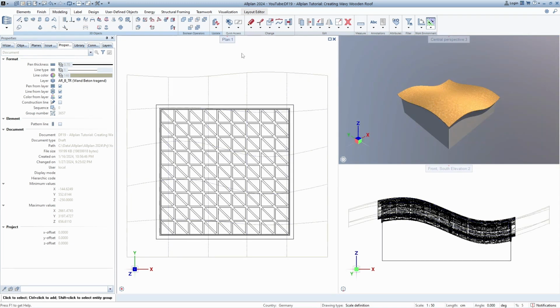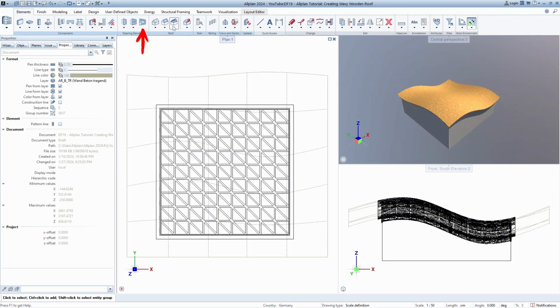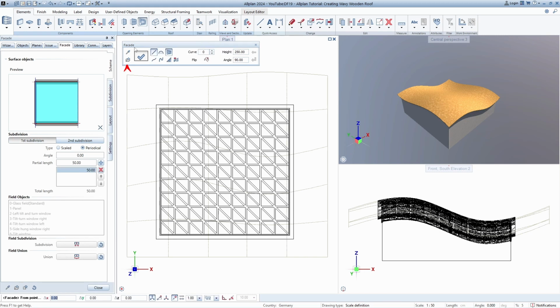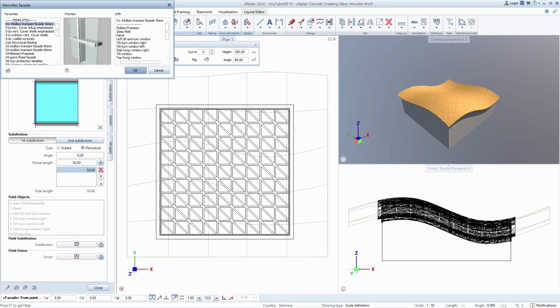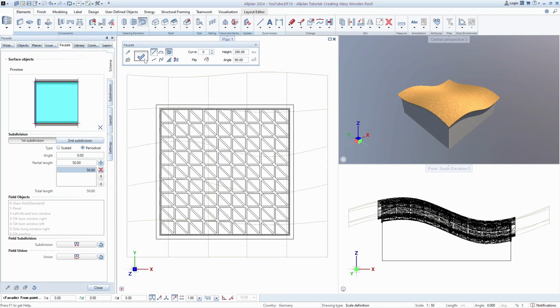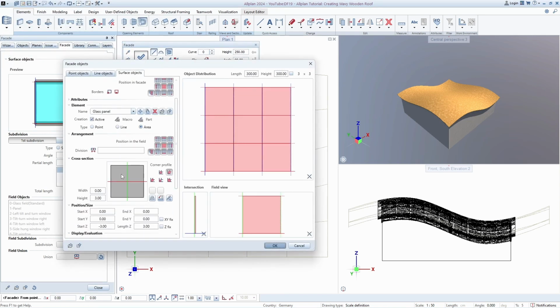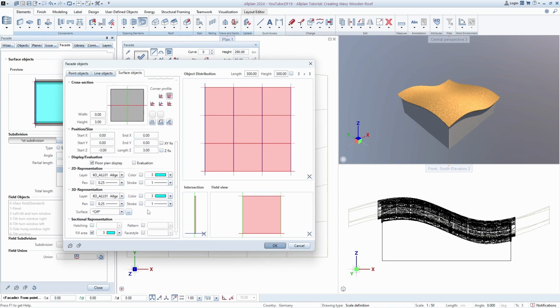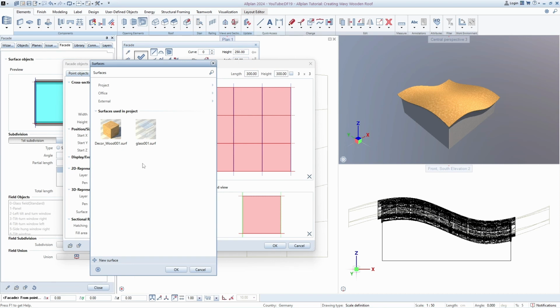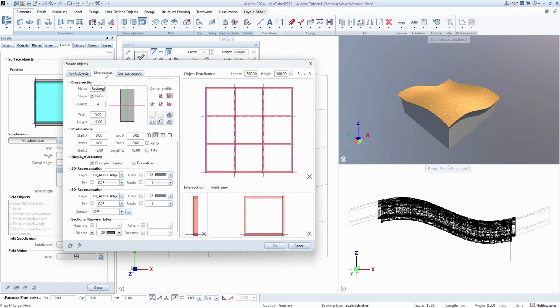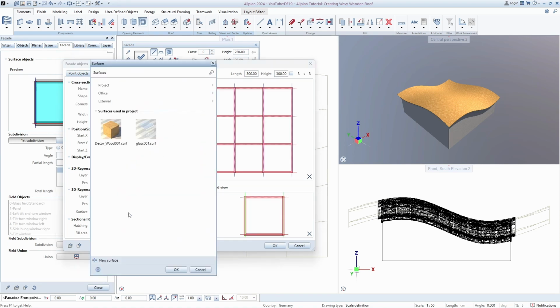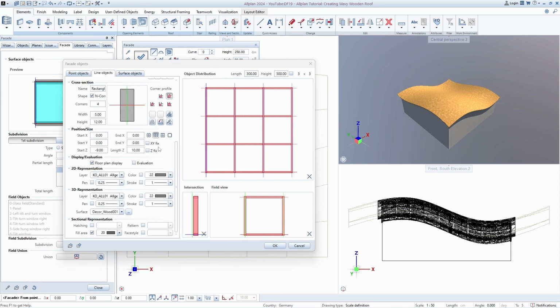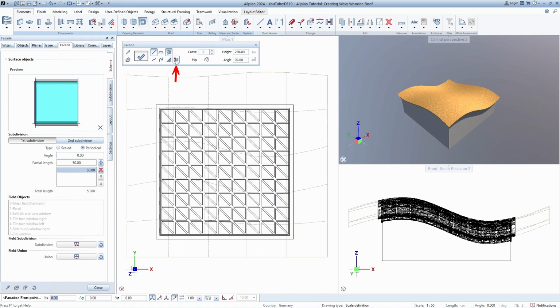Now let's find and run Facade tool, and it's a really good thing that this tool has templates, otherwise this video would be much longer. Choose structural glazing, and if you open the settings you will see a lot of options, but they are not the topic of this video and we will only assign surface to our elements. Add a transparent surface to the glass, while for the frame we will use the same wood surface that we have used so far. Let's go to OK, then to the Select 3D Surface option.